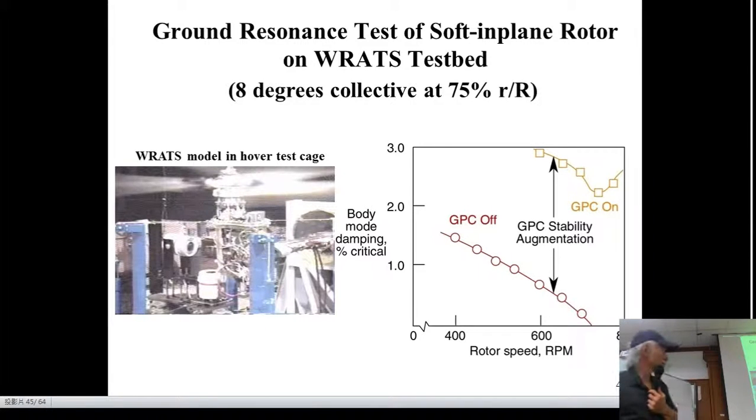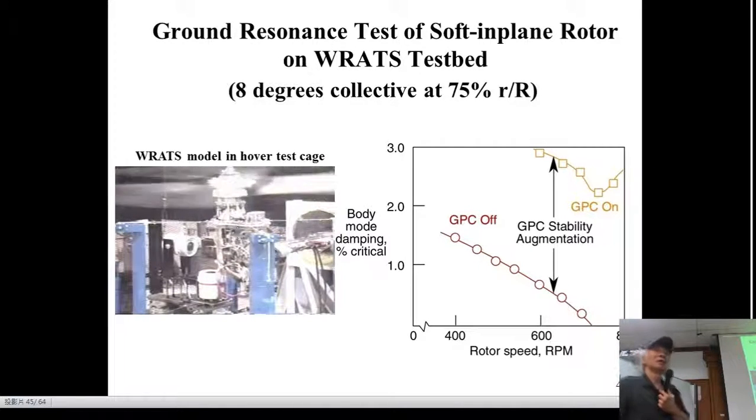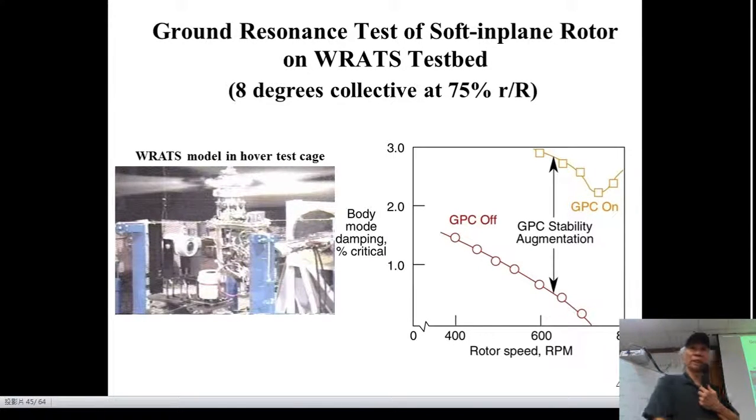Did you see that oscillating? I'll play again. All right. So the rotor speed is keeping moving up. This is speeding more. Comes up to about 750. See, if you don't turn off, that will break. The vibration is too much for the whole system.